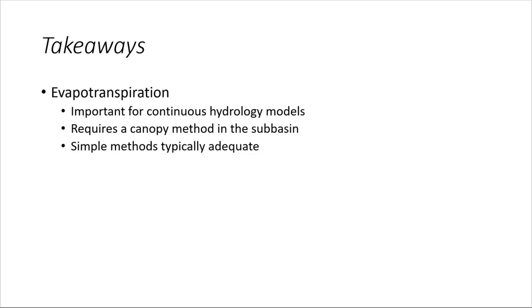Here are the three key takeaways for evapotranspiration modeling in HMS. First, ET is an important part of continuous hydrology models. Second, in order to compute actual evapotranspiration, a canopy method is required for your subbasins. Finally, the simplest methods for ET and canopy are typically adequate. Use methods with fewer data requirements where you can.